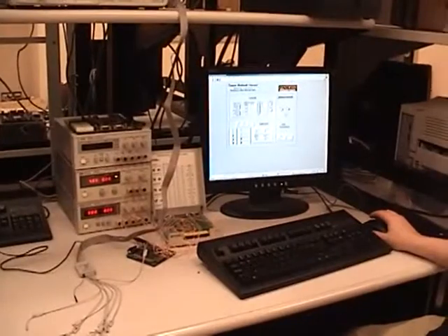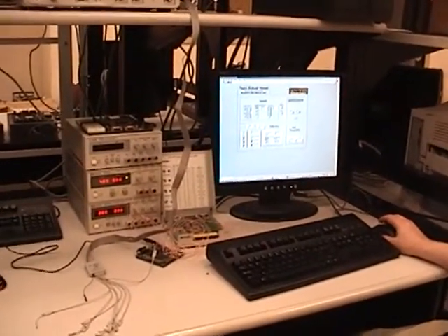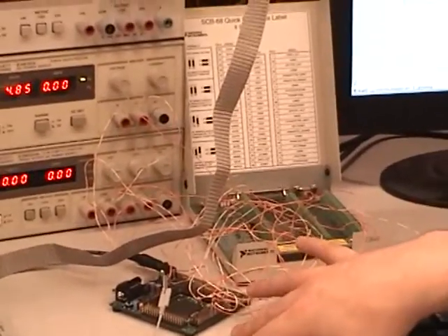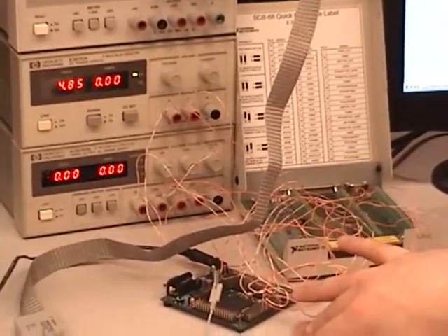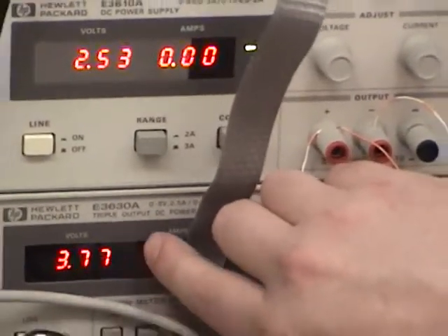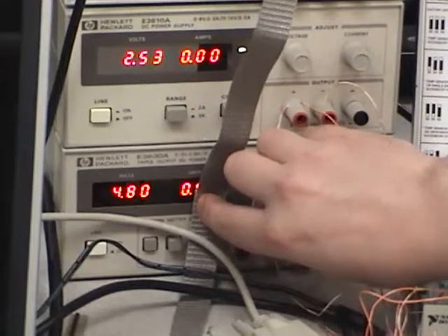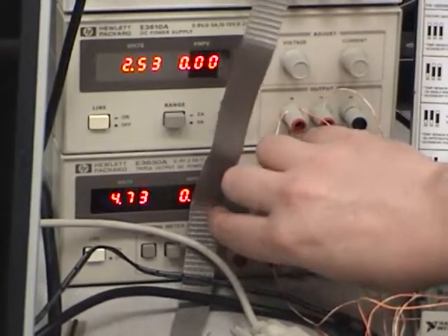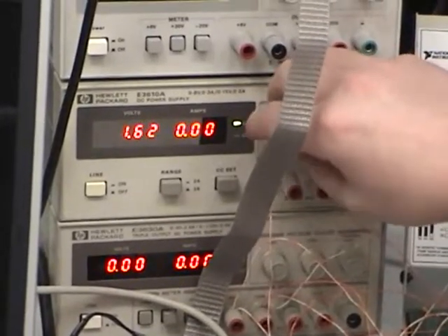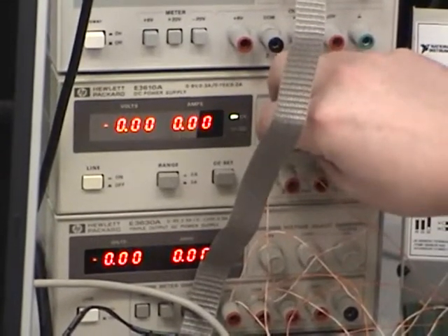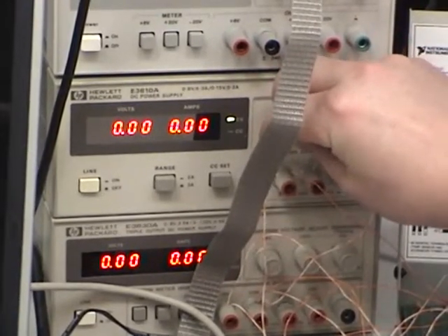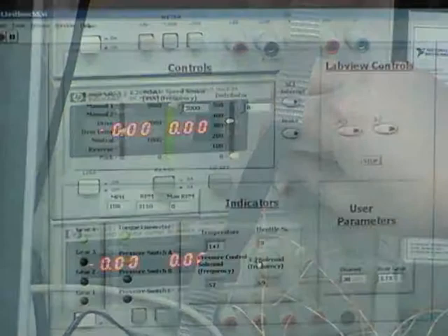All right, this is the LabVIEW simulation that we created to analyze all the logic of the microcontroller and what our program is doing as we developed it. It goes between 0 and 5 volts, which represents 0% of the throttle being pressed down to 100% of the throttle being pressed down. And this is the temperature, which also goes between 0 and 5 volts, 0 volts being negative 30 degrees and 5 volts being 302 degrees Fahrenheit.